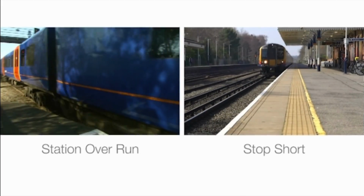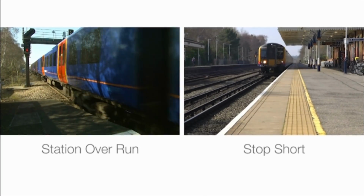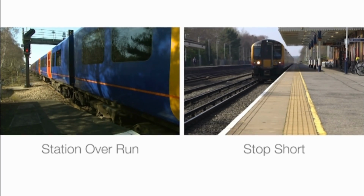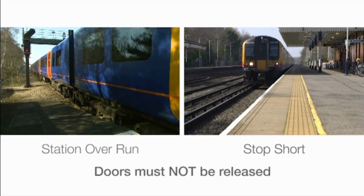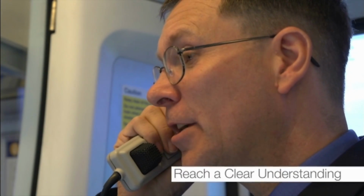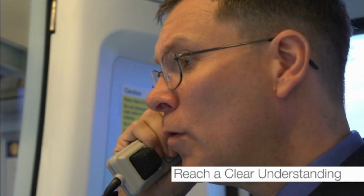The ASDO system cannot detect station overruns or stop-short incidents. Therefore, doors off the platform could open. If an overrun or stop-short incident was to occur, the doors must not be released. The guard and the driver must reach a clear understanding about how the incident should be dealt with.